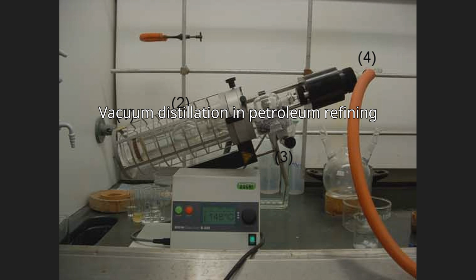The absolute pressure of 10 to 40 mmHg in the vacuum column is most often achieved by using multiple stages of steam jet ejectors. Many industries, other than the petroleum refining industry, use vacuum distillation on a much smaller scale.